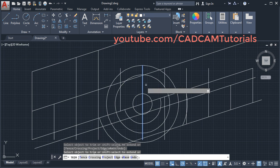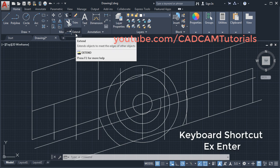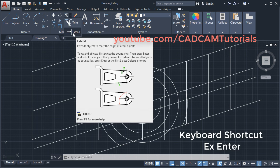So during trim, if you want to extend, you don't have to give the extend command. You just press shift and click on the object you want to extend, and to stop the command press enter. So in this way you can use trim as an extend also. And if you want to give the extend command directly, then you will have to click on this arrow here, and here is the extend command. The keyboard shortcut for extend is EX, enter.